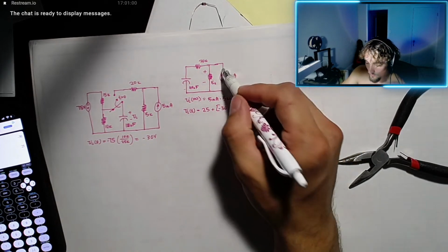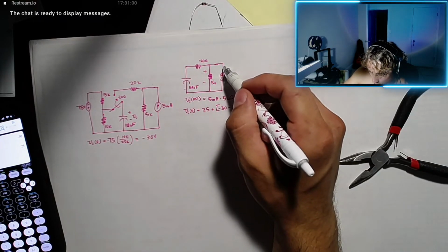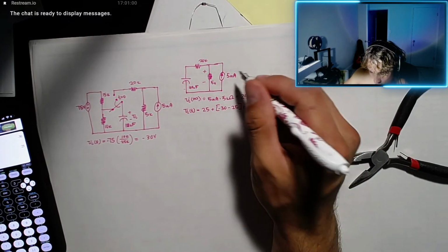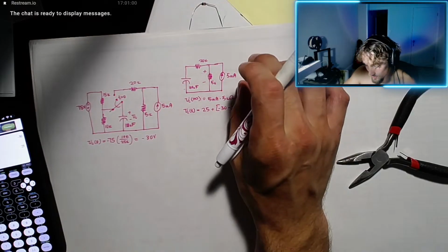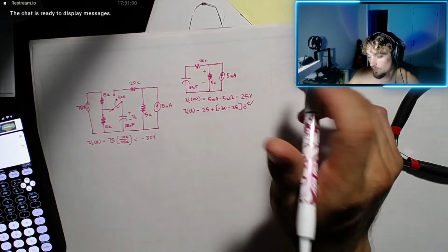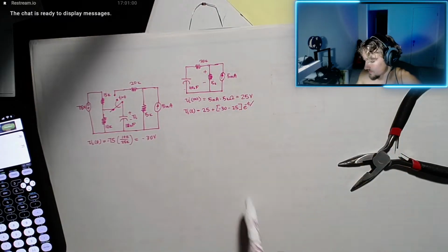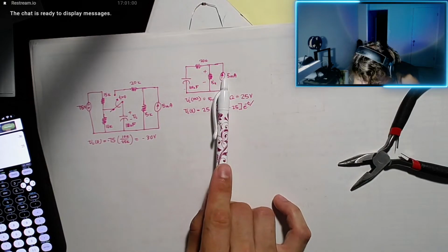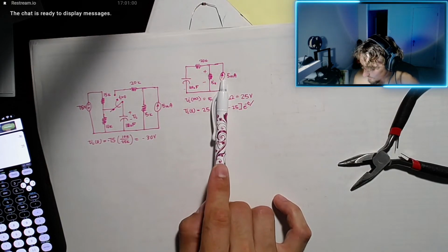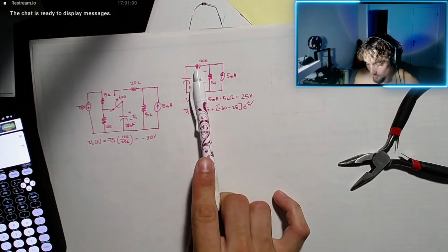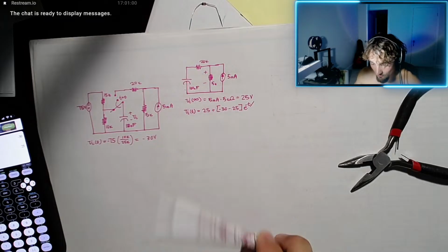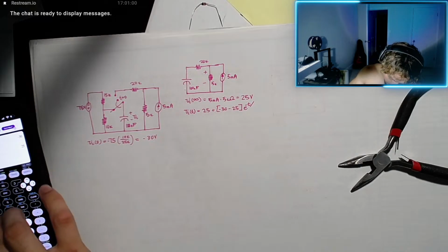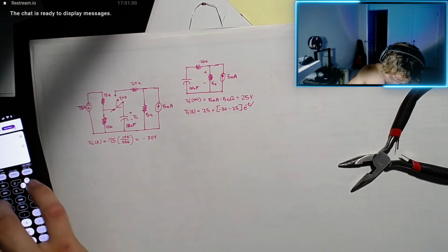So if this was an open circuit, what would our RC be? What's going to be our R? It's the resistance perceived by the terminals of the capacitor. To find the complete resistance perceived, we would convert this current source into 0 amps, which would be an open circuit, no current flow. And we would simply have these two resistors in series. So 25K, 25 E3 times 100 nanofarads.